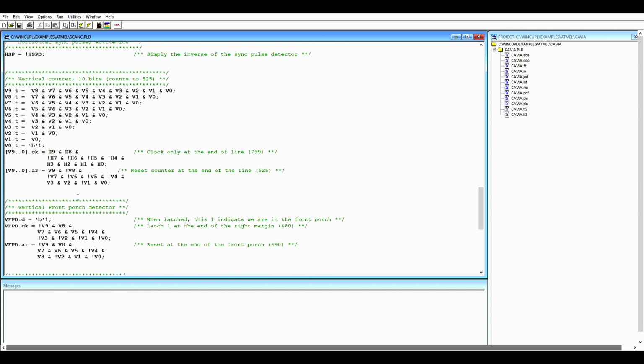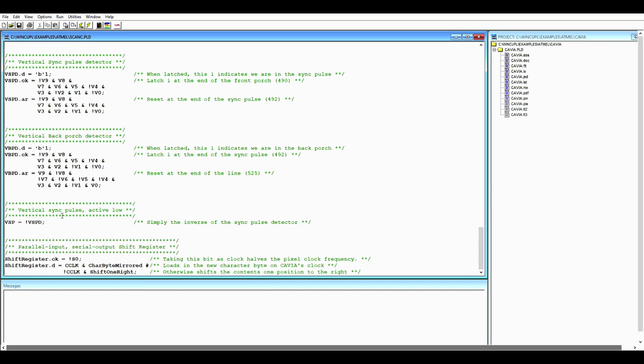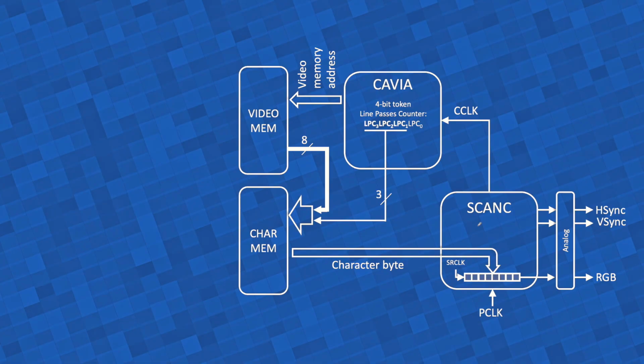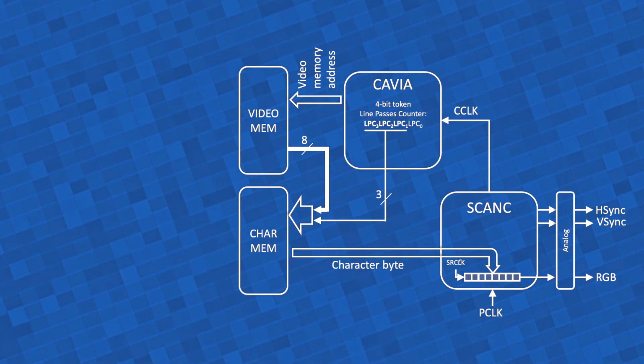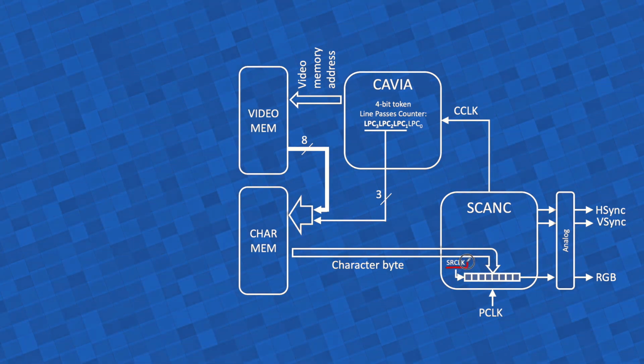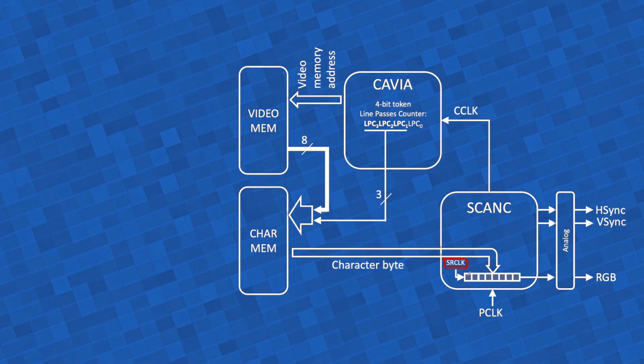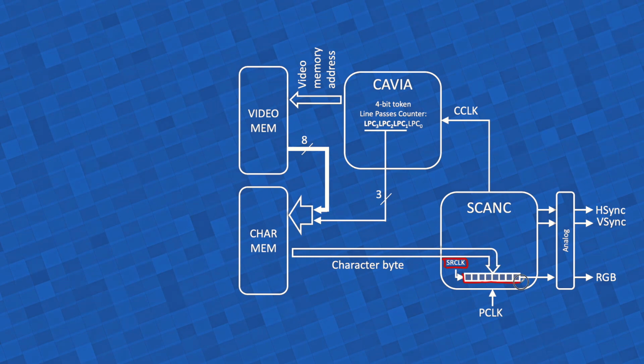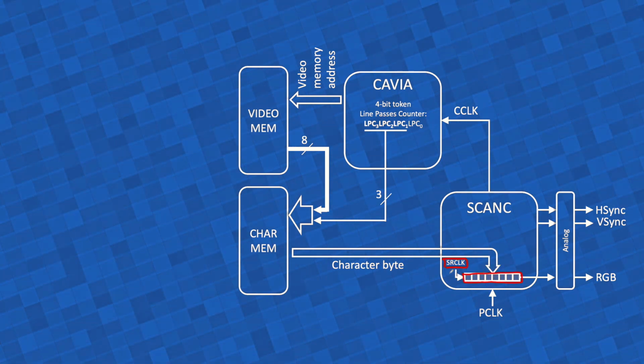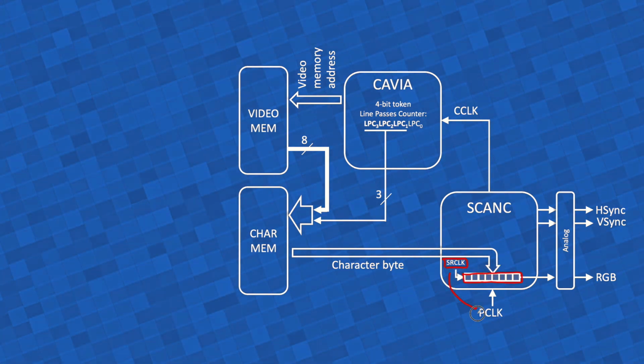There is one more thing that I have changed, and it's all the way here. Before I had the negation of S1 as the shift register clock. Well, that doesn't work for reasons that I've explained to you right now. The challenge, if you remember, is to generate a shift register clock signal here to drive this shift register with half the frequency of the pixel clock.